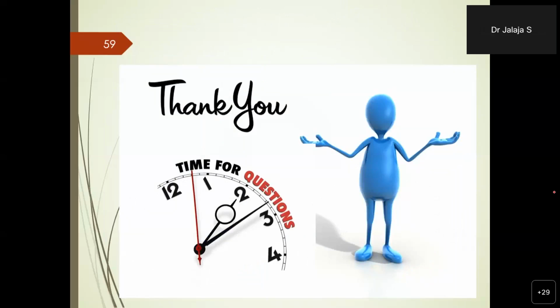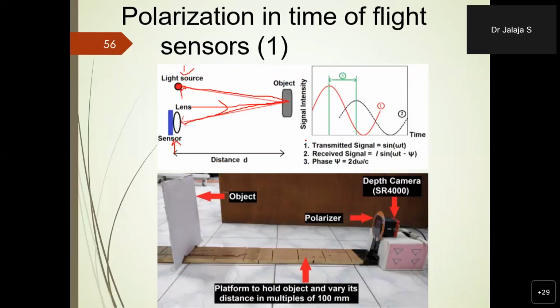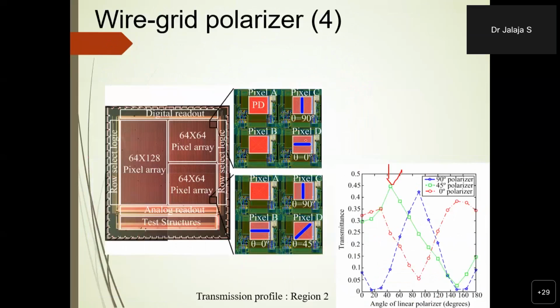Sir, one question from my side. The pixel noise you are talking about, how is it going to affect power dissipation? So usually, in order to keep the pixel noise lower, you have to burn more current. If you want your source follower pixel noise to be low, then you have to bias it with a very large current, right? And therefore the pixel power increases. The power consumption increases.